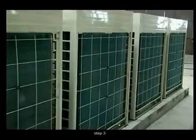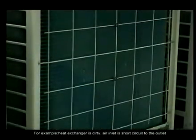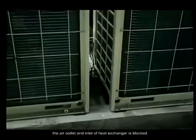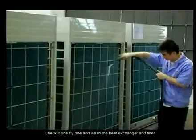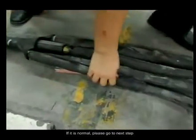Step 3. Check if the outdoor unit has poor heat transfer. For example, the heat exchanger is dirty, the air inlet is short circuited to the outlet, the outdoor fan doesn't work or wind speed is too low, the air outlet and inlet of the heat exchanger are blocked, or the distance among the outdoor units is too short. Check it one by one and wash the heat exchanger and filter. If it is normal, please go to the next step.